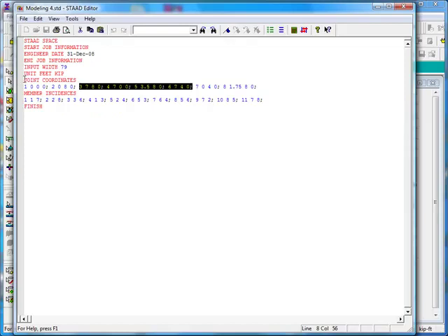And then there's also another color that I can show if I insert an asterisk before any line, which is the way that we indicate a remark statement in Staad.Pro. It uses green to indicate anything that it interprets as a remark or a comment, meaning something that will be ignored as the input file is read in and processed. I'll just delete that asterisk to restore the joint coordinates command now so that our model actually makes sense.